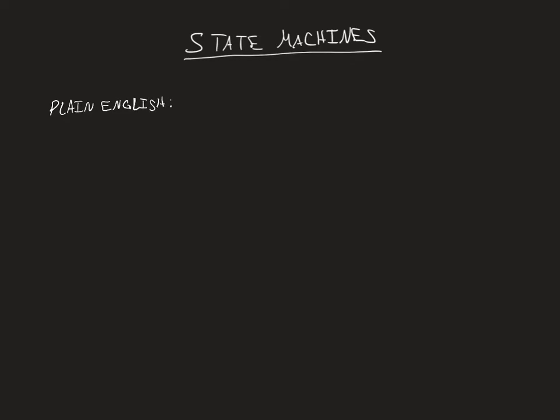All right, what we want this state machine to do is we want to have two states, S1 and S2, and when you're in state 1 and you get the input T, we're going to transition to S2, and when you're in S2 and you get the input T, we're going to transition back to S1. When you're in S1, you'll give output S1. It's a Boolean output to designate that you're currently in S1. When you're in S2, you will give a Boolean output called S2, designating that you're currently in S2.